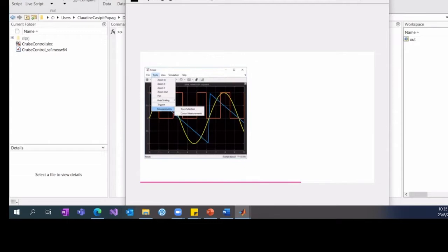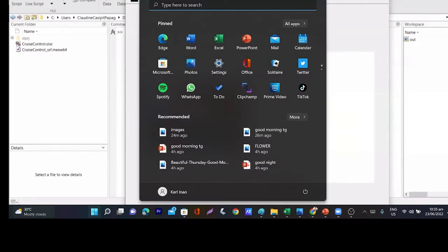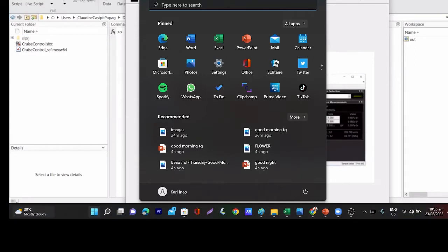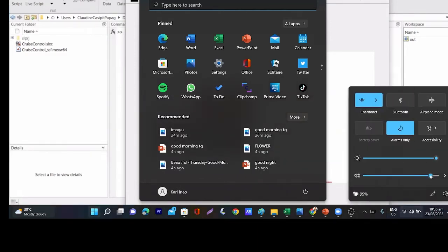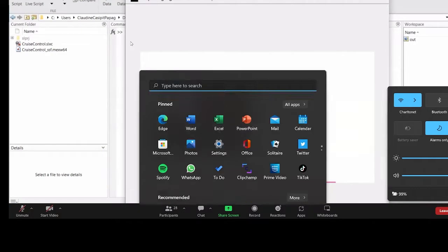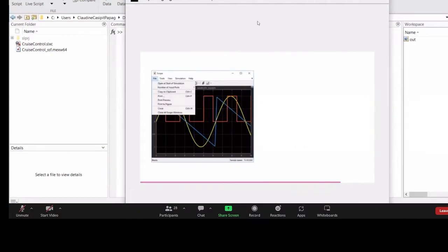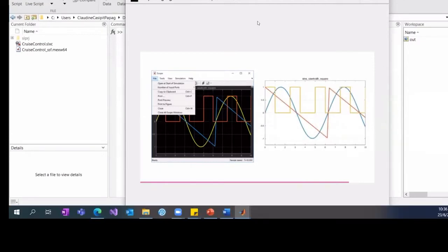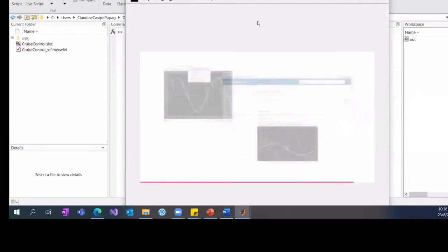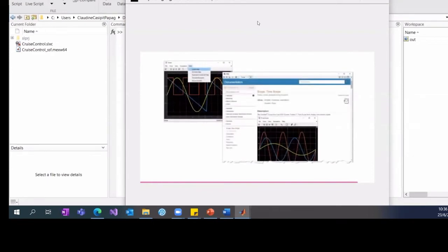If you have toolboxes other than Simulink installed, you may see additional menu items here. The cursor measurement window allows you to trace signals and estimate the period or slope between 2 points. If you want to share your simulation results with others, you can export the scope images using our print and copy functionalities. The copy to clipboard option adjusts the colors of the scope image to make it appropriate for including in other documents. If you want to know more, use the Scopes Help menu to access the scope documentation page.